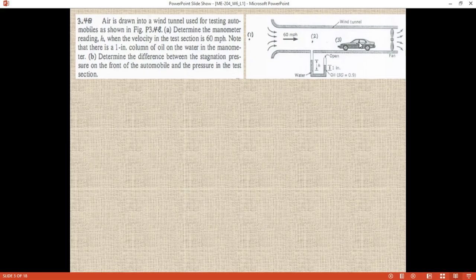Okay, so based on that, if you want to maintain the pressure, you can increase or decrease the RPM of the fan. If you want to increase the temperature of the air, so you can put some heater or something in the wind tunnel to maintain the temperature. So there is a different setup based on the requirement, what test you want to do. So here we want to see the impact of air pressure on the automobile.